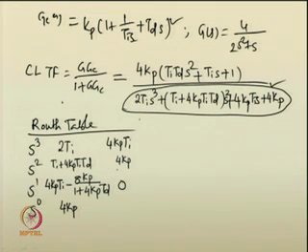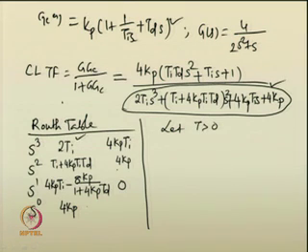So, the closed loop system will give us a stable time response when all the coefficients of the first column have the same sign. So, let me assume Ti is greater than 0, then this becomes positive. When Kp is greater than 0, then this becomes positive, and when Kp Ti Td is greater than 0, Td is also greater than 0, we get this coefficient as positive. What about this coefficient?